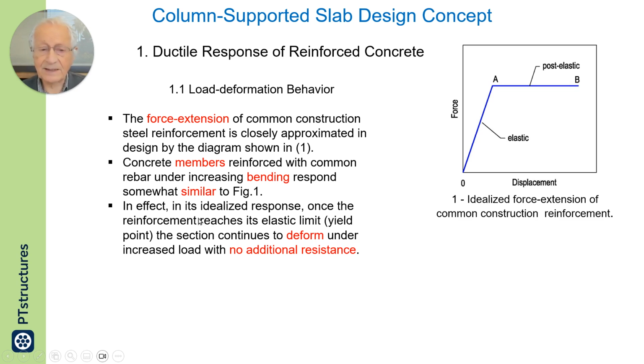In effect, in its idealized response, once the reinforcement reaches its elastic limit, yield point, the section continues to deform under increased load with no additional deformation. I have to be more specific here.